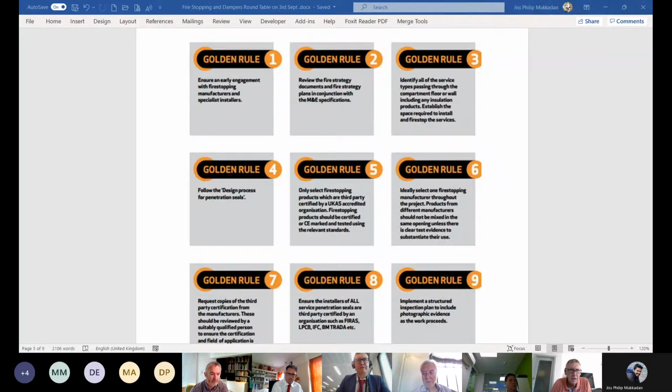Absolutely. In part 3, it's not so bad because the market has gone away and tested soft seals, which are like an 80 kg product over a 140. But in dampers and ductwork, the test is, Paul, you can shoot me down in flames if you want, so prescriptive. Essentially, testing a 4-sided hull. As soon as you go into a flexible wall, the fire safety of the flexible wall kicks in. If you look at how the wall is built, as soon as you've got 25 or 30 mil deflection, you end up with a 250, 60 mil deflection head for the fire safety of the wall. No one takes account of that, which is why everything goes down on sites. Or people do 3-side approaches on site that aren't tested with a deflection head in there, so it's not right.